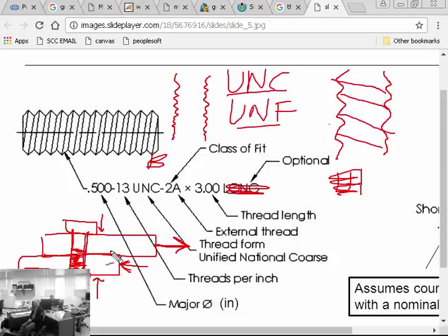And why is that? Why do we want to sandwich these things together super tight? Friction. We basically create internal friction, which also helps resist the motion. Okay? That's why we have all these standards about how much you're supposed to tension your bolts. In ideal scenarios, you get these things right about to the point where they're going to fail.